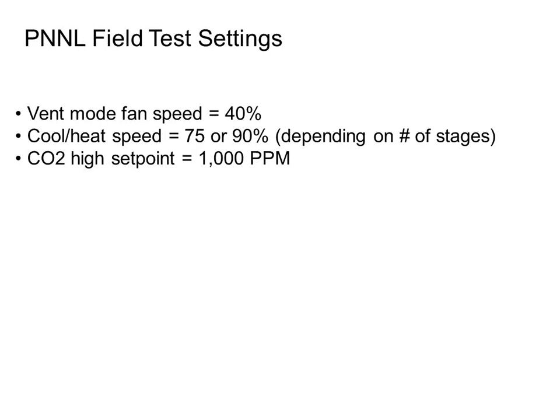Now, you can argue 75%. In many cases, you can go a lot lower than that. But as just a safe number for them to pick, that's what they did. I suppose they could have done a study on each individual product at the sites and perhaps gone down into the 60s or even 50% airflow range. But if I'm on one stage of heating and cooling, run 75%. If I want 2 stages of heating and cooling, the maximum, then run at 90%.